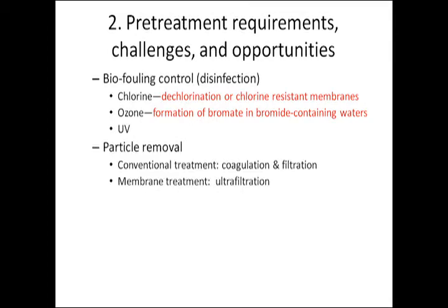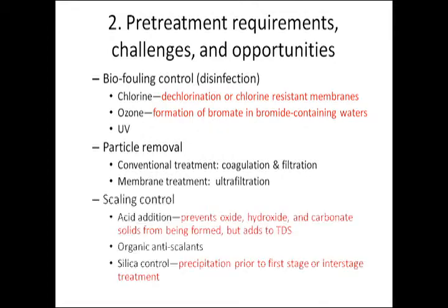Another area is just particle removal. Very few waters are perfectly clean with respect to particles, and oftentimes pretreatment has to use conventional drinking water treatment processes, coagulation, and oftentimes ultrafiltration membranes to prepare the water for RO. And then a big issue with respect to reverse osmosis membranes is scaling control.